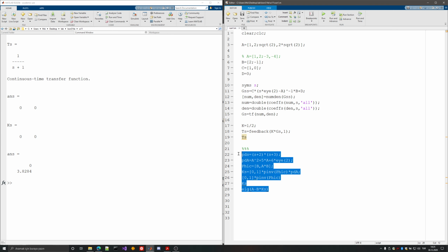So the pseudo inverse or the Ackermann formula is not usable if you don't have full rank controllability, which means that the system should be totally controllable. If that's not the case, then unfortunately you will not be able to calculate it. You have to maybe reduce your model, since most probably you have unnecessary states defined.